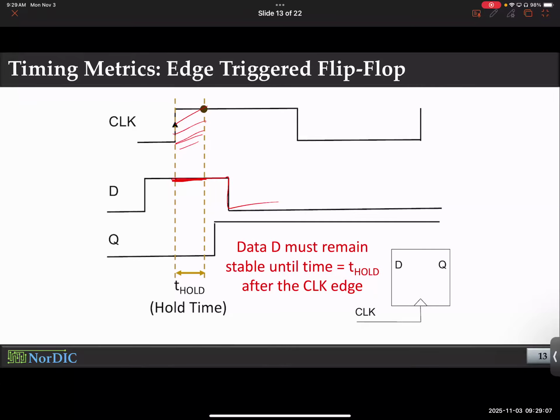So you have to let it finish charging. Even if you want to go back to 0, that's fine. But first let it finish charging, go to VDD so that you don't get stuck at an intermediate stage. Okay, let it finish charging. And then you go down to 0, it will discharge again. It doesn't mind. The capacitors don't mind. They will charge and discharge the way you say it. But you have to let them finish what they started.